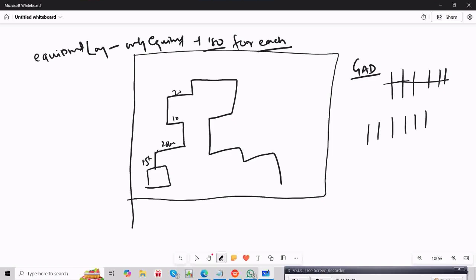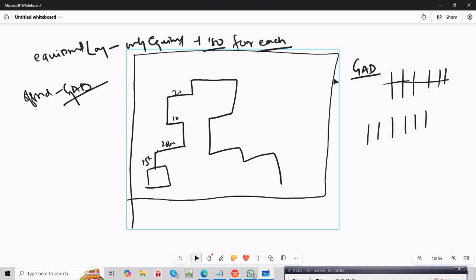On the off side, you generate GAD, only GAD, no isometric. So in the outside area for construction we refer to the GAD. Inside the unit plan we refer to the isometric.